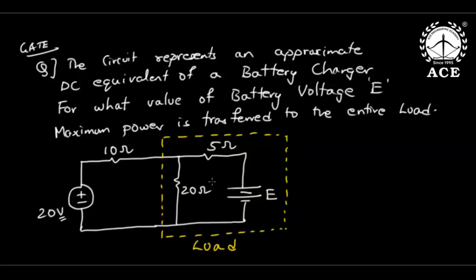See here, in this case, there is also a battery. This yellow box line is a battery charger, because this battery charger has an internal resistance and also a voltage regulator. Because this is a DC equivalent, he gave the voltage regulator as a resistance. So this battery charger has a current limiting resistor and also a voltage regulator drop. Please understand this.